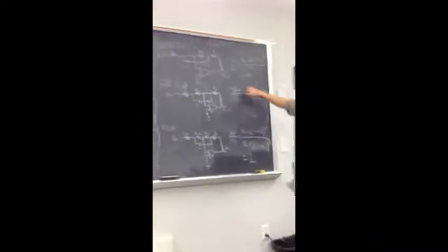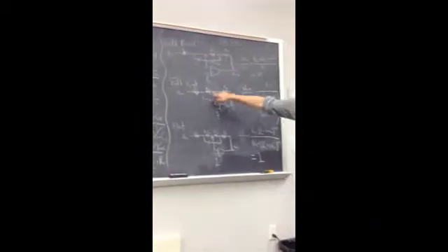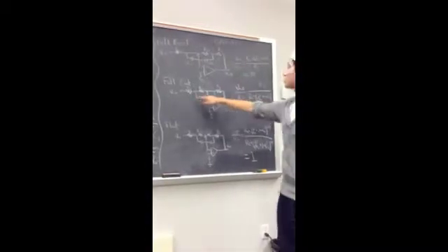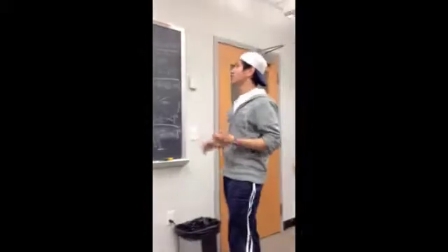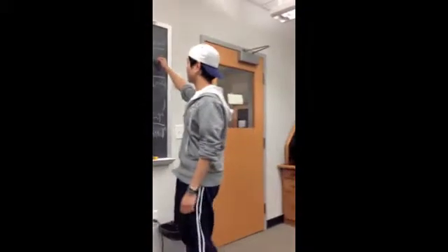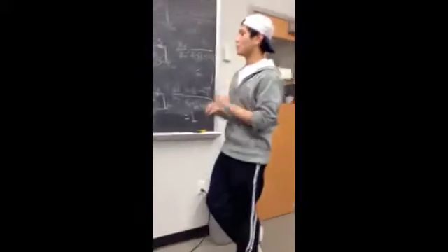For the same values here, we would need our potentiometer to be around 9 to 10 times larger than the value of each one of these resistors, so that we could achieve the ratio of impedances that will give us the 10 times and the 1/10 gain. And there is where we made our initial judgment of values.